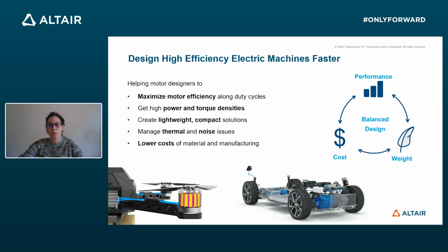E-motor design is not a simple task, so we normally have to meet multiple goals and respect multiple constraints in an early stage of the design process. We deal with multiphysics constraints such as noise, temperature, and of course electromagnetic efficiency. And we normally have to find the best compromise between cost, performance and weight, manage thermal and noise issues, and get high power and torque density, increasing the motor efficiency along the duty cycle. So FluxMotor is the tool that allows us an efficient machine pre-design and quick performance evaluation.